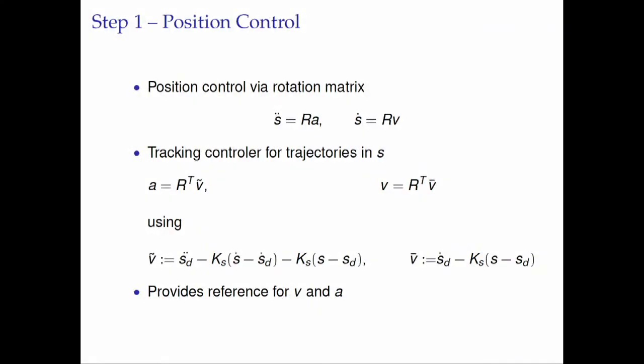So what you do now is you use your rotational matrix, so just R is the rotational matrix, to do your position control. We define our position in that nice trajectory by defining a new input, so we have some gain matrices where you do just some pole placement, so you move everything to the left half plane. I was confused with that. So that you have nice poles and everything is stable.